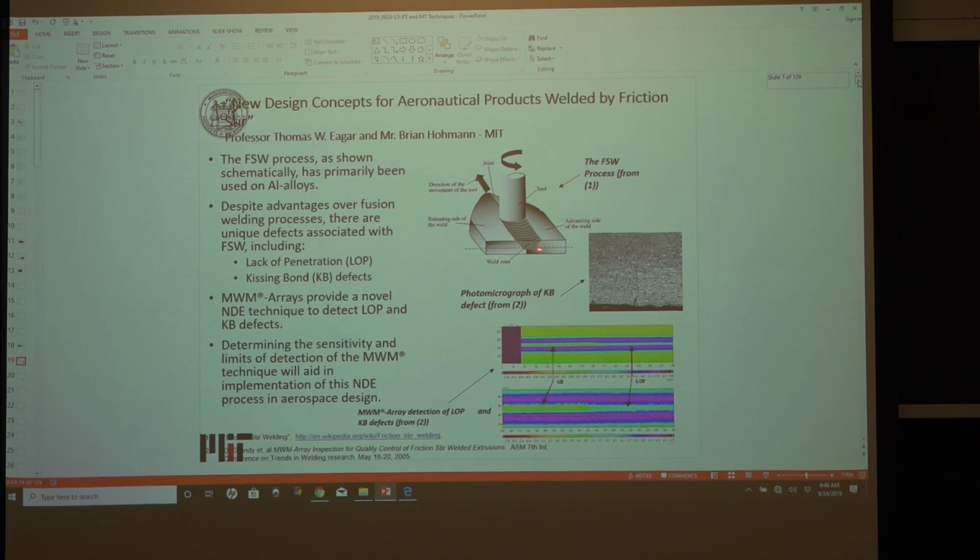This is the friction stir weld right here. You have the crown of the weld and the root of the weld at the base here. And what you're seeing is, as you scan over it, you can see the heat affected zones. This is known as the nugget of the weld. So the nugget is the central area here.